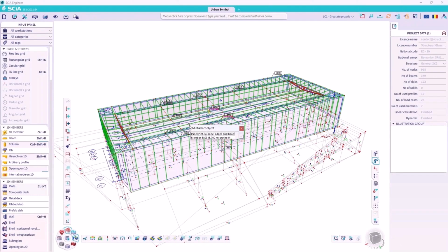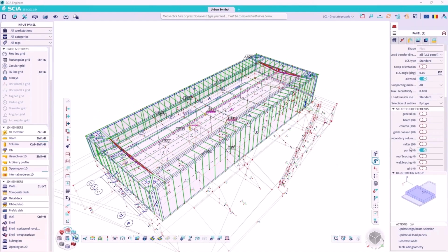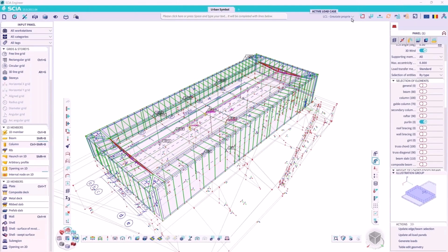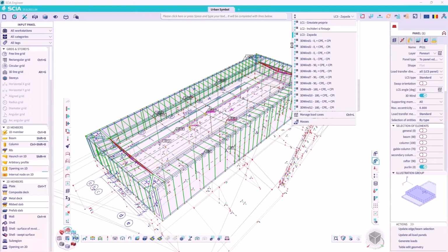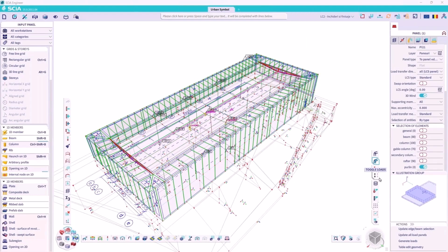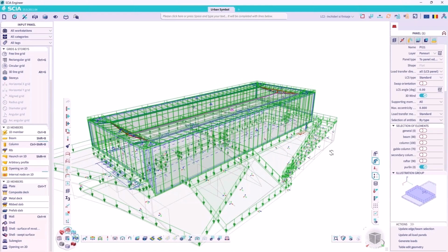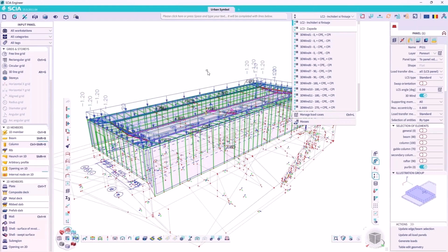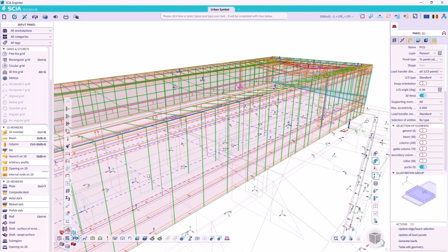And the next step is we insert panels. So we cover the structural members with panels. And these panels don't have any kind of stiffness, but they just redirect and calculate the tributary area for each 1D member, so it transfers correctly as we would expect. So one quick example is not to load the roof bracings with gravitational loads. So aside from the self-weight, we don't want to position snow on this bracing. This bracing should look on the automatic 3D wind generated data.